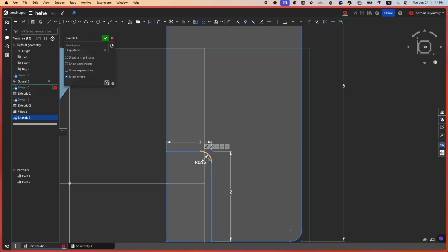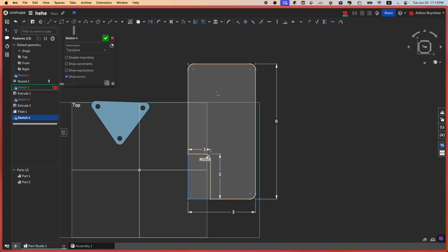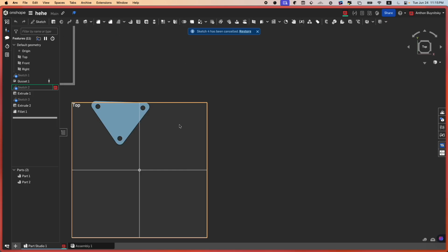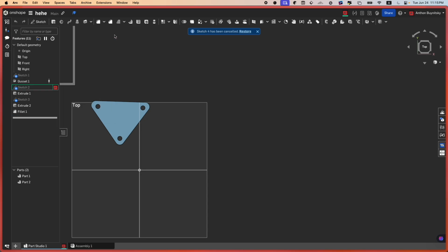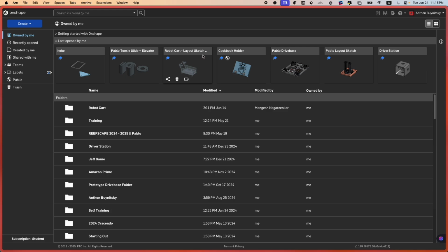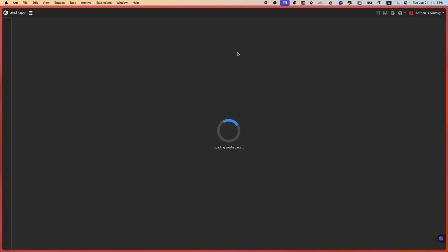Especially when you have a lot of them, and when you have them on a pretty technical part, it makes it pretty difficult to change the natural dimensions of your part. So I highly recommend doing fillets after you've created the original rough sketch or rough draft of your part, because they're supposed to be an add-on feature anyway, and that should also save you some regeneration time.